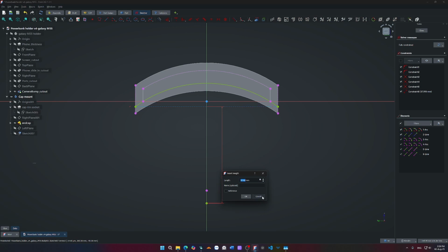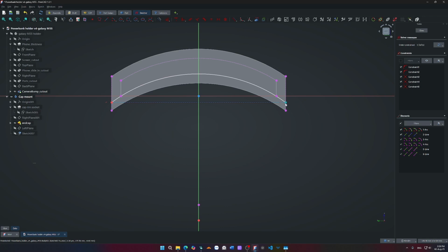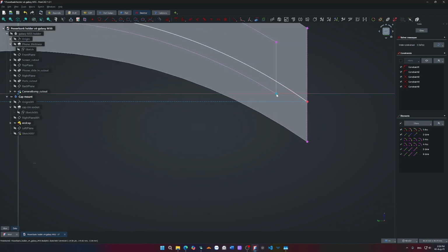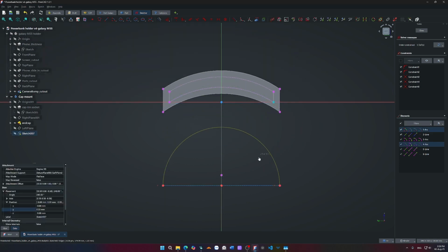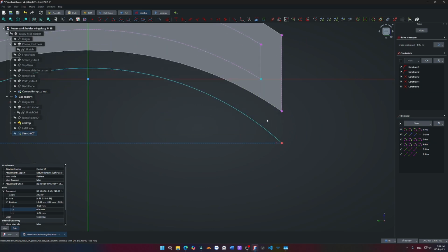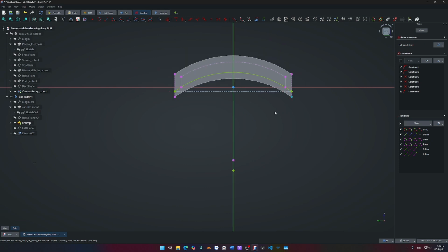Okay, the distance is pretty strange, to be honest. It's not 40 millimeter. It is not the extension of the arc, but it is something else. I will try one more operation, that is to set up the coincidence from this point to this line to see if it gets better. Yeah, I think this will solve it. Okay, yep, very nice. This shouldn't be needed, to be honest.